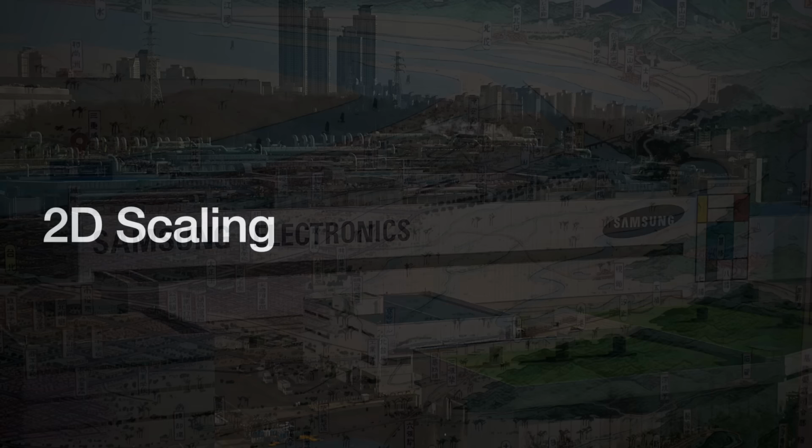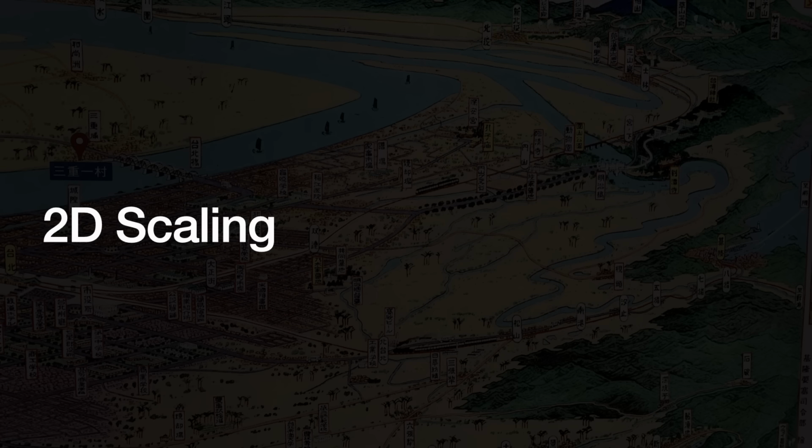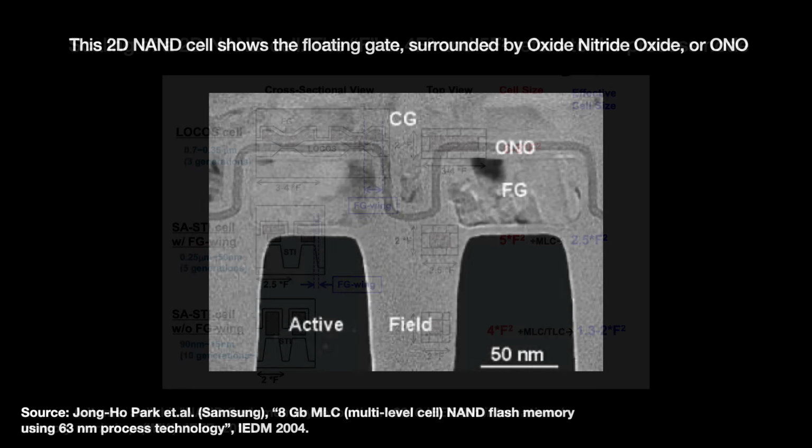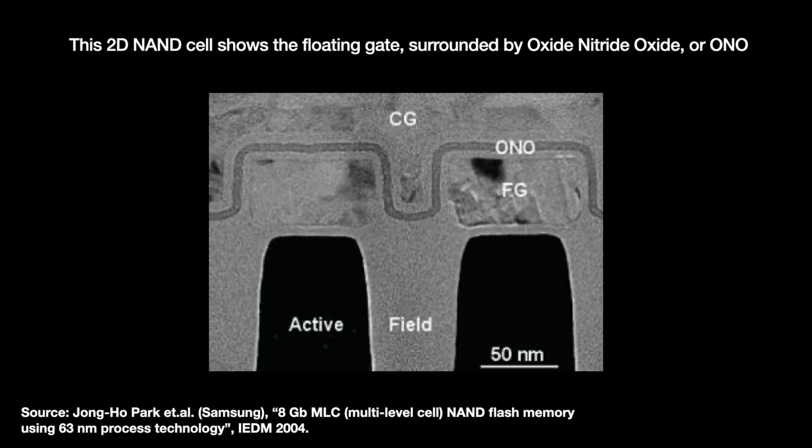Reaching the cheapest per bit cost in the 2D NAND era was achieved with 2 levers. The first lever was to follow Moore's law, shrinking the transistor's physical dimensions so that we can stuff more cells together. The second lever, commercialized in the early 2000s, are multi-level cells capable of storing 2, 3, or even 4 bits inside a single memory cell by segmenting the threshold voltages into buckets.